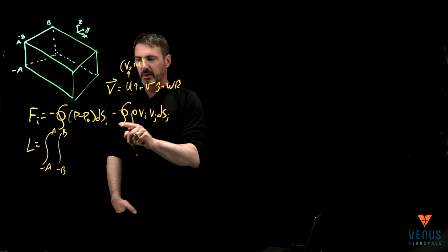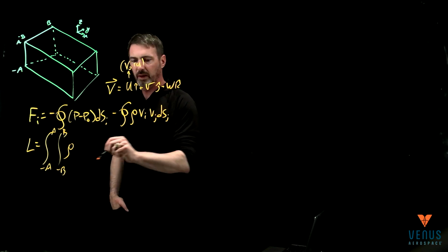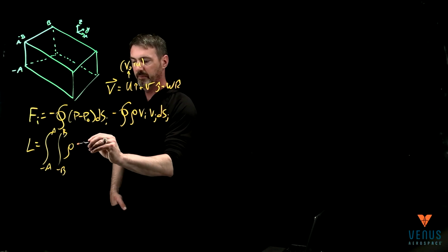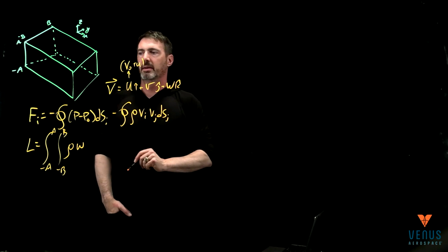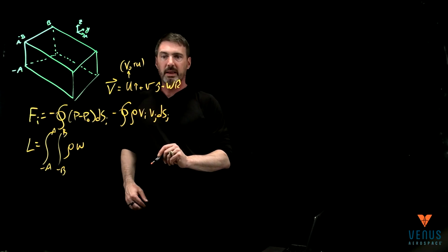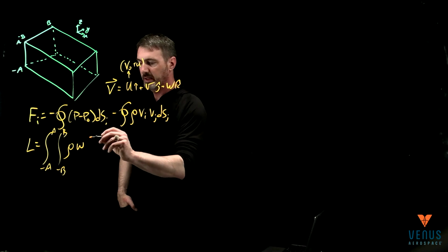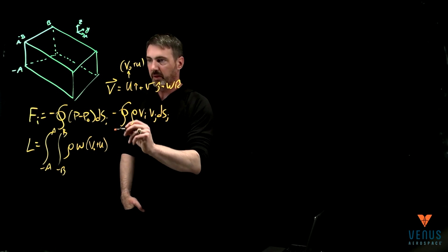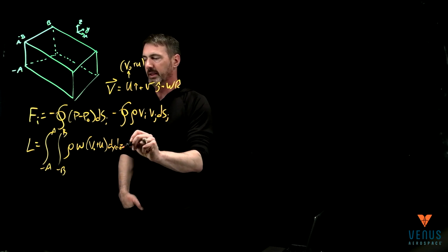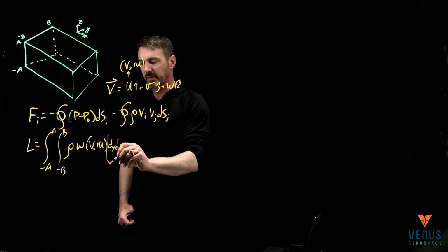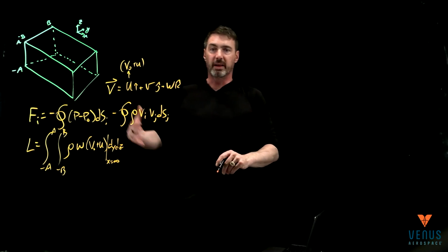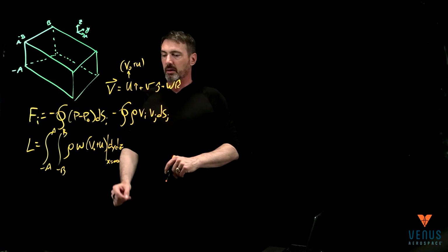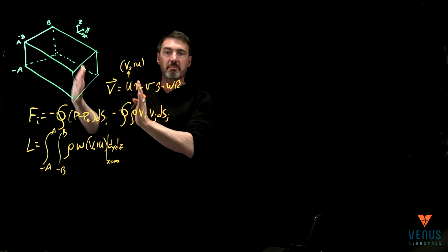You would have, since it's the lift direction, rho, the lift is z direction, so vi is actually just w. And then the amount coming out the back plane is what's the velocity being dotted into that? That's v0 plus u into the back plane. Back plane is then just dy dz with those limits of integration. And just a reminder, this is actually at x equals, we'll call it infinity, this back plane, infinity. So that's the portion on the front and back walls.